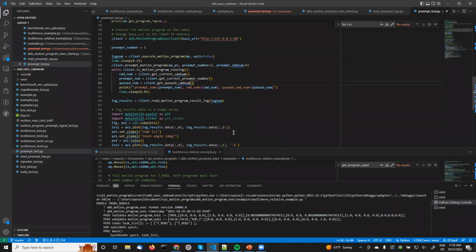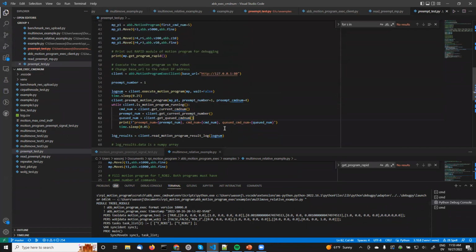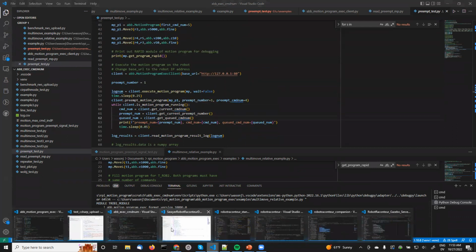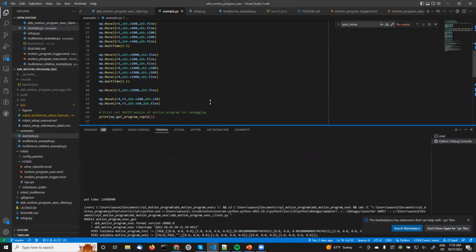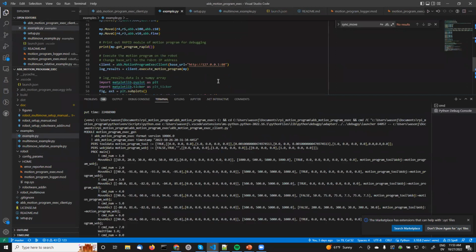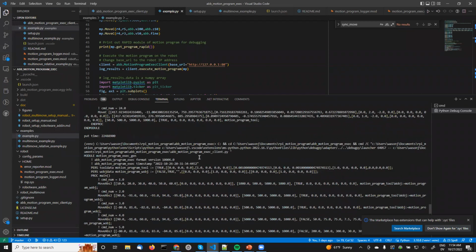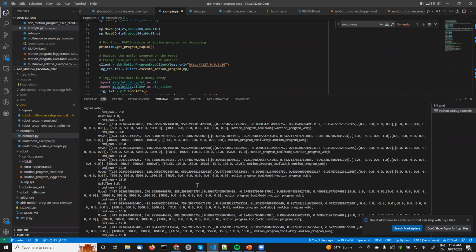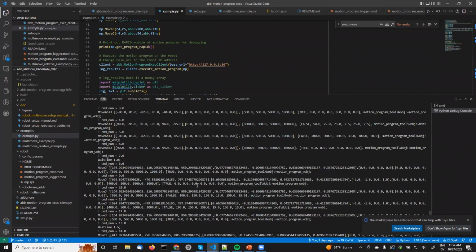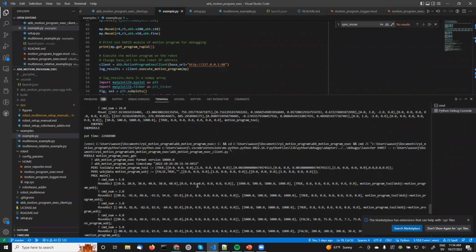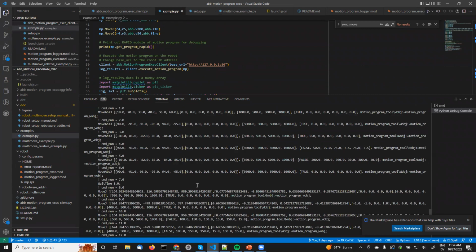Yeah, so actually this does exactly that. So move back to the other command example. If you look at the printout, for debugging purposes, we had it so it can generate out RAPID code. So we already have that capability now. This isn't a driver, this is just a Python library right now. The driver's coming. But this has the ability to generate out RAPID directly from the commands you send to it. So that's definitely a feature we have. Now we're going to be doing the same thing for MotoMan in the next project.